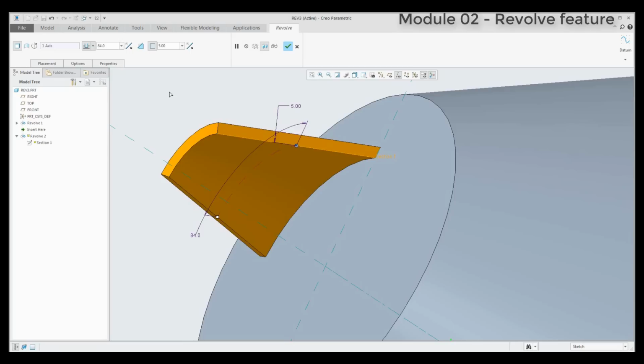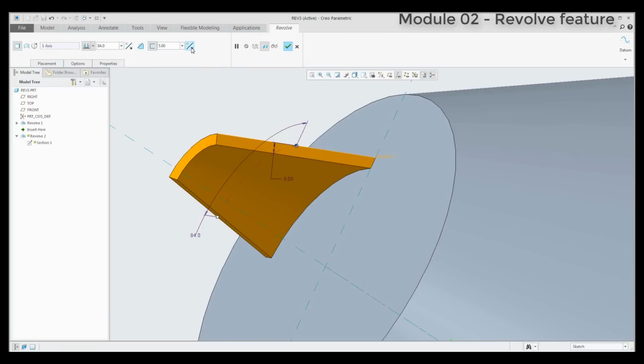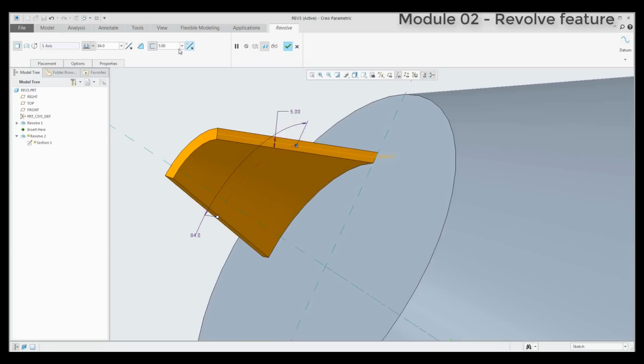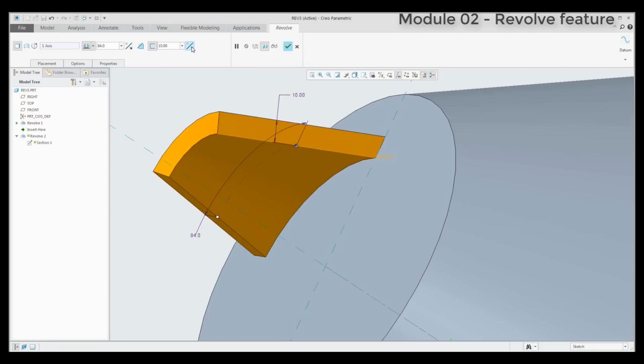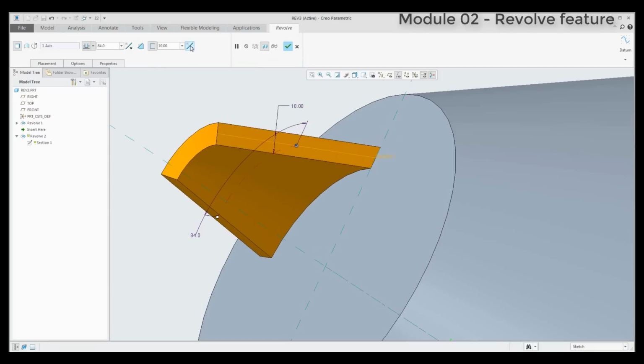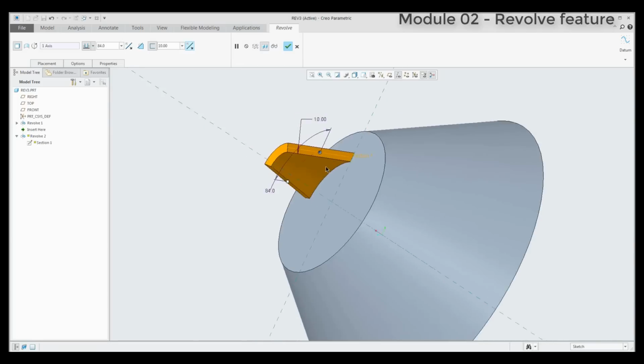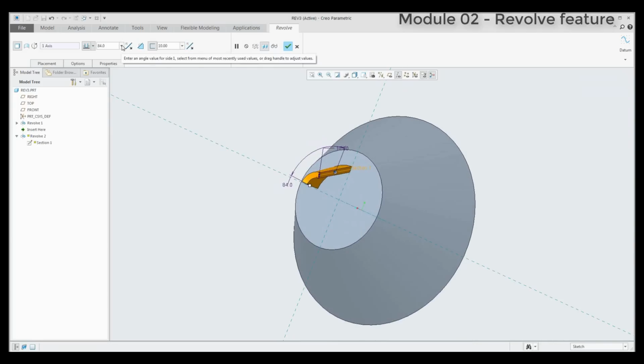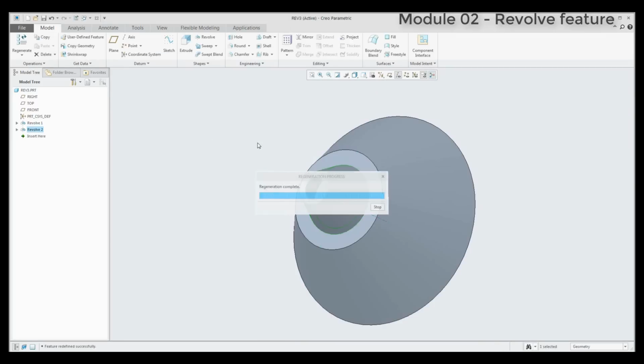And how it works: if you create only a line or an open sketch, you can specify that you would like to add material as a solid model with a specified thickness. The system can add material on one side of the sketch, or inside of the sketch, or symmetrically. So if I specify a different thickness again, you can see here I can go outside from the sketch, inside from the sketch, or symmetrically.